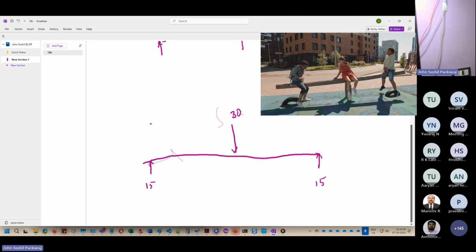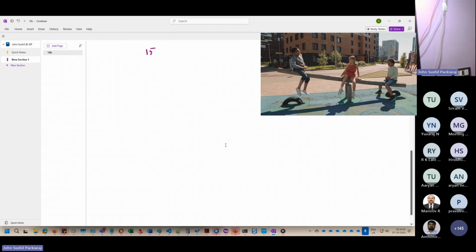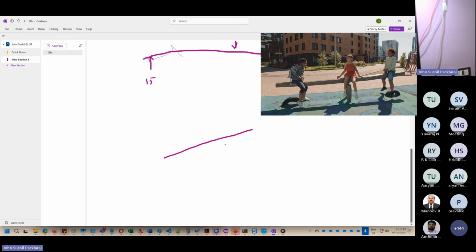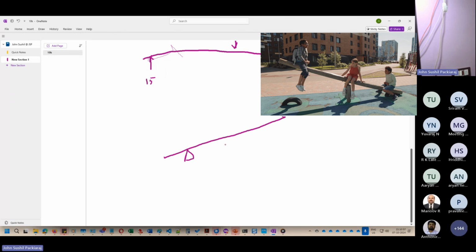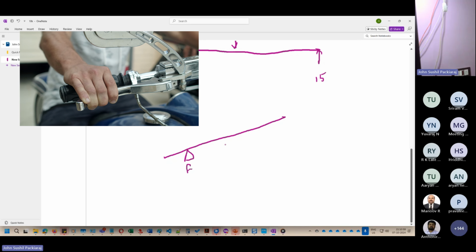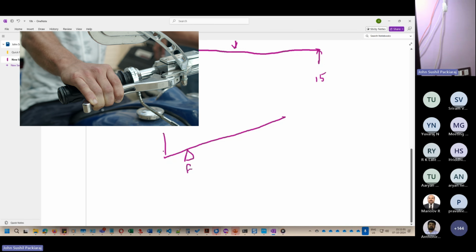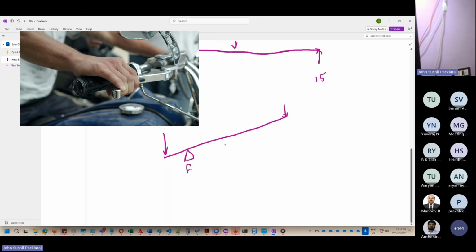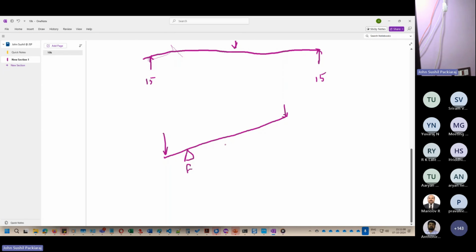And if we are not having the load equally present, let us say that we are having a small lever. Here there is the fulcrum. So we know that the load into load arm is equal to effort into effort arm. Automatically, you'll say that a small value of force will be able to take a large value of force over here.